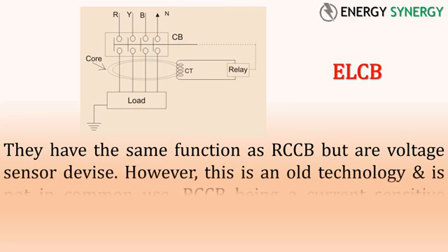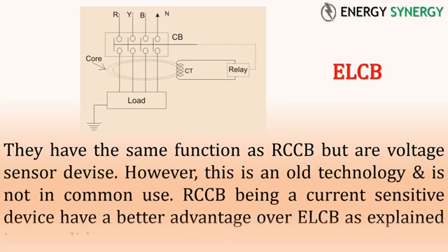ELCB stands for Earth Leakage Circuit Breaker. They have the same function as RCCB but are voltage sensor devices. However, this is an old technology and is not in common use. RCCB, being a current sensitive device, has a better advantage over ELCB, as explained in the next slide.